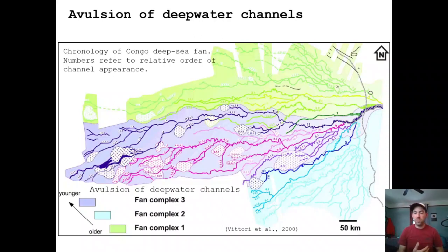So in a river system, we've talked about bed load and suspended load. They're relatively low concentration flows. We talked a little bit about how the velocity profile looks for a river system and how that manifests itself in how the river transports sediment, right?